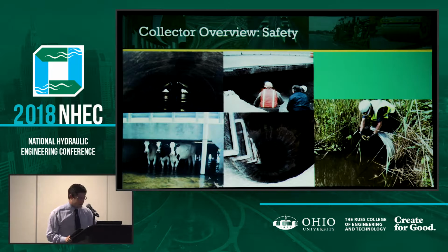Oh, wait, one of my pictures is missing. That's all right. In Ohio, mainly, we deal with high water. We deal with confined space. We deal with lots of things, cows maybe. But mainly we want to inform the inspectors when they're going out to a culvert that they may need to bring safety equipment. They may need to take a tripod or air monitor with them in order to keep them safe and in order to make it more efficient. You would hate to go out to a culvert and not be prepared. So that's another great use of the collector program.